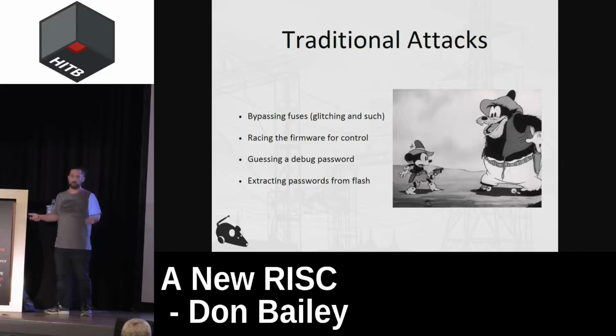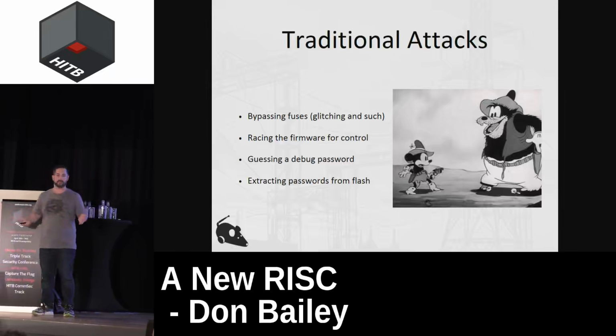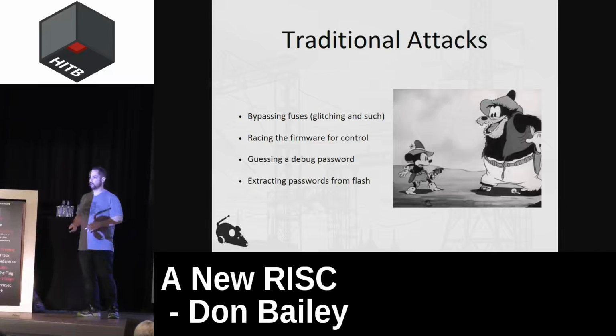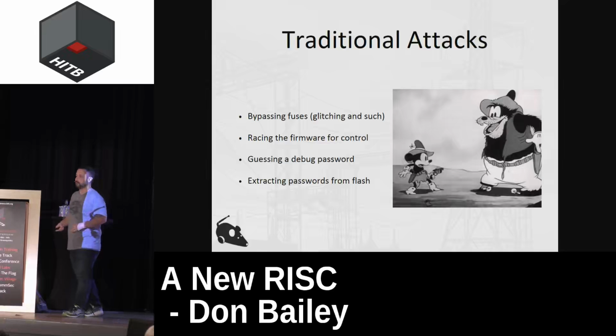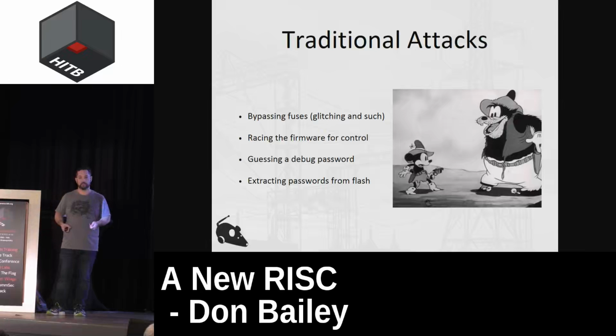It's really that easy. In most cases, you see system on chips that are being sold en masse, especially Wi-Fi chips for IoT. They have two attack models that are extremely popular, where I get code execution with nonstop. Most clients that have this model, I end up just recommending that they go with a completely different architecture because this is a waste of their time. But basically it's, oh, there's a password. That password can be easily found through sorting through Flash.